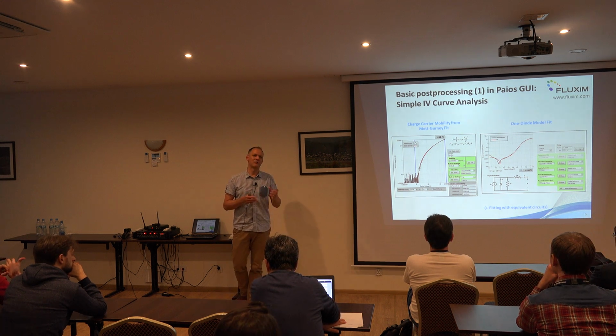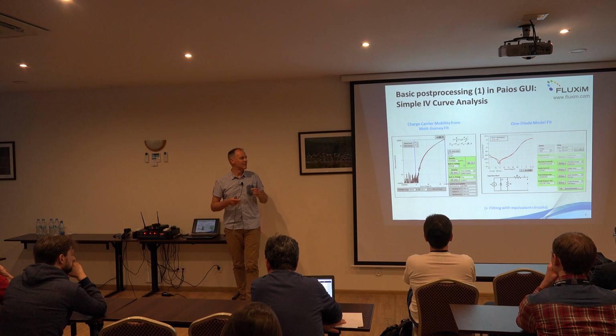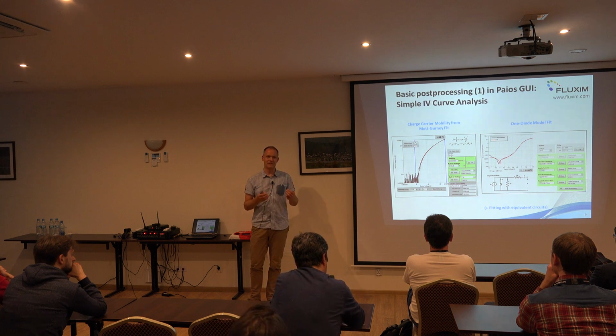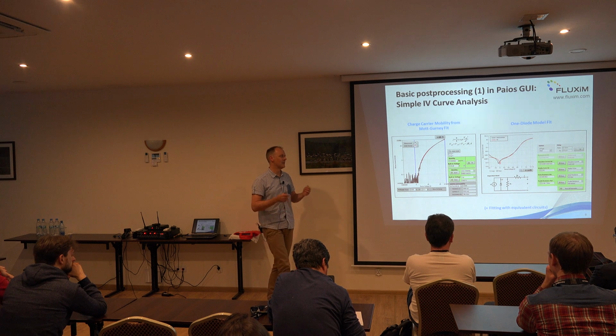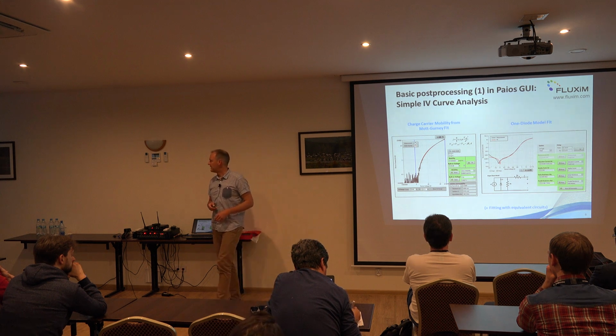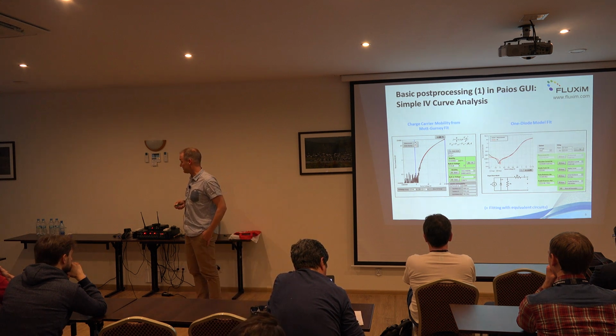So if you have a lot of resistance, the signals get slower, and that's happening in the measurement. And if you want to successfully describe this with a model, you also need to know the value of the series resistance to put into the model, meaning the drift diffusion model. You need to have a good estimate of these series resistance, for instance.